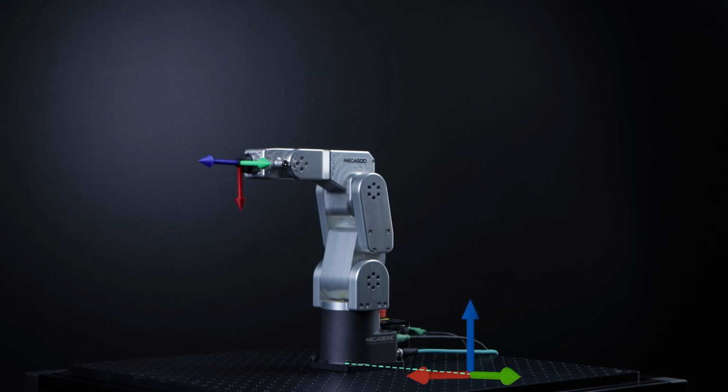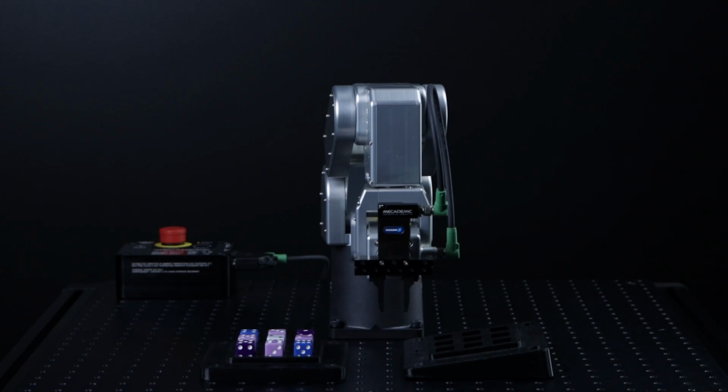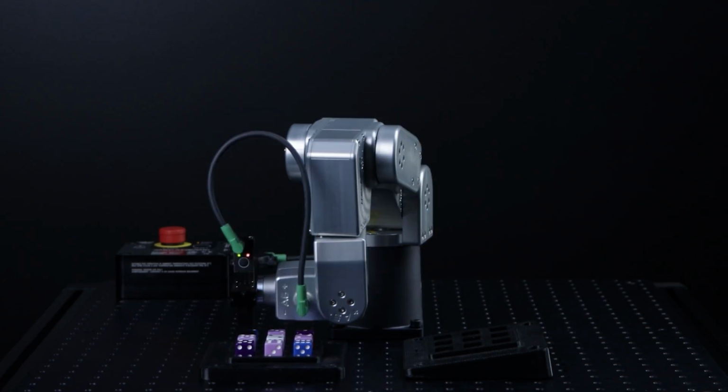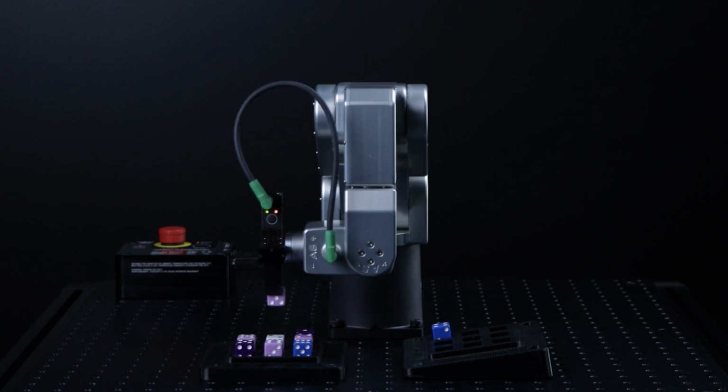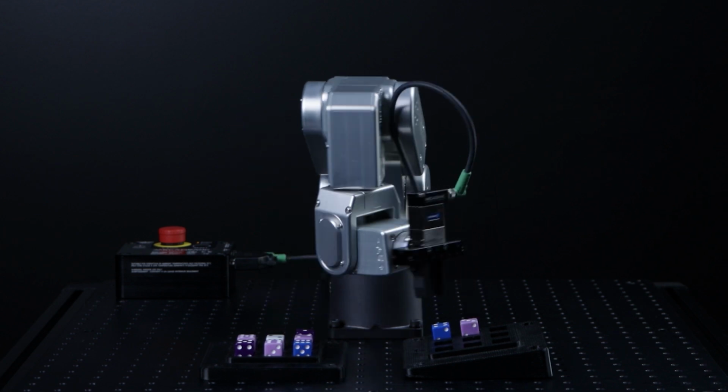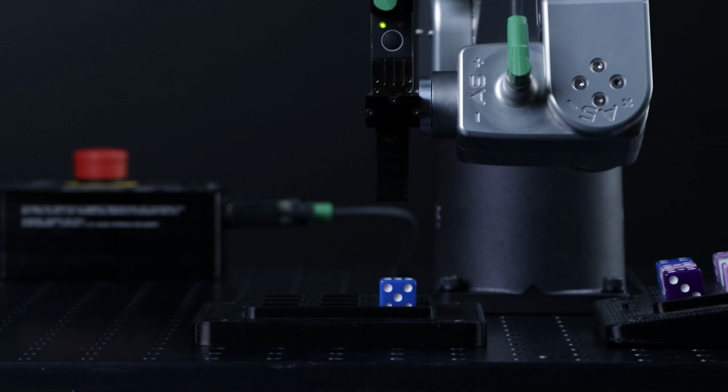So every time you call the command, the position will be set with respect to the base frame, not the previous definition of the WRF. This is extremely useful, especially for code reusability. A good example would be a grid-based pick-and-place application. Let's first start with the pick sequence in tray 1. It would probably look something like this.